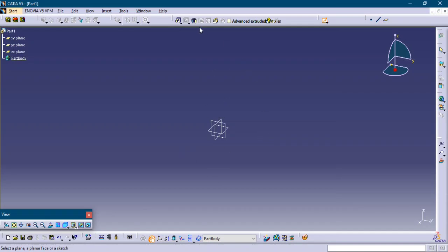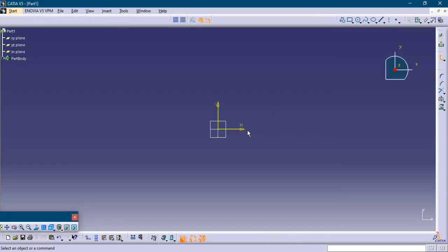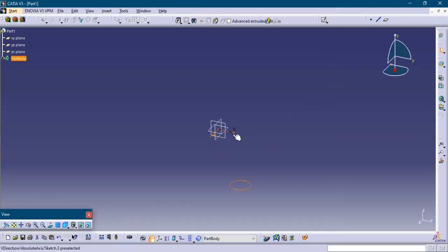I have selected only sketch and I chose a plane. Here I'm choosing this normal sketch option and this front plane. Okay, top plane I have selected, so no problem. Let's see, I was drawing a circle here and exiting from this workbench. There is a symbol here. So see the position of this circle. See where I have drafted, somewhere like here, but it is projected here. So this is a problem with this sketch option.